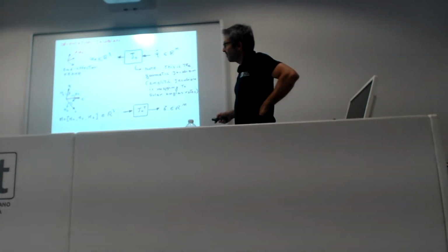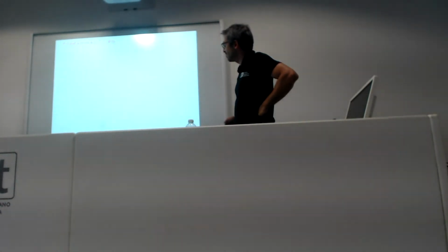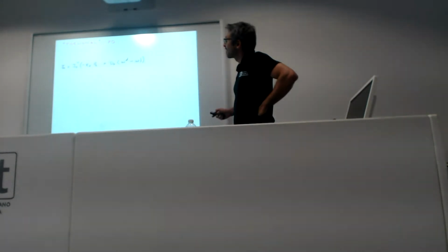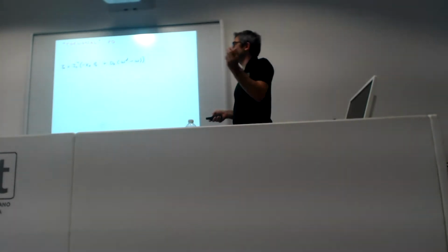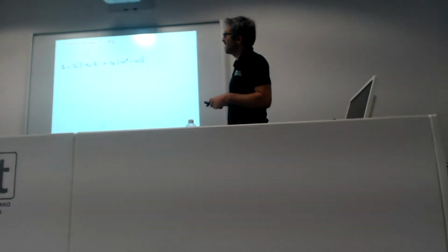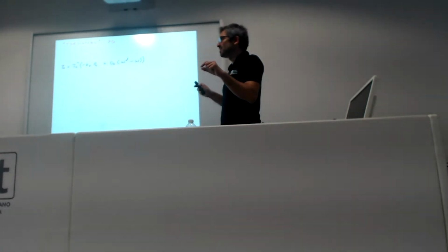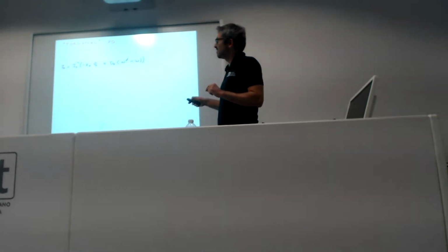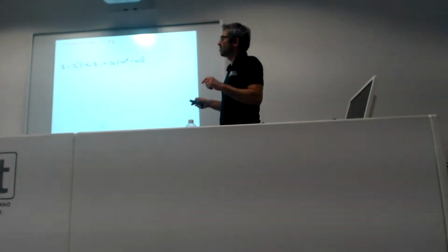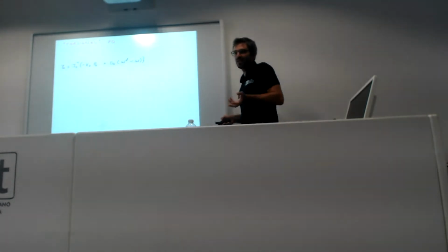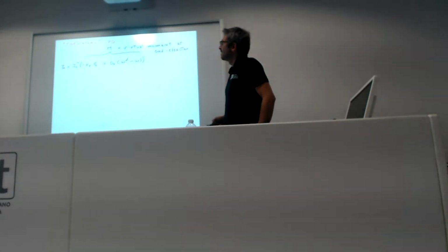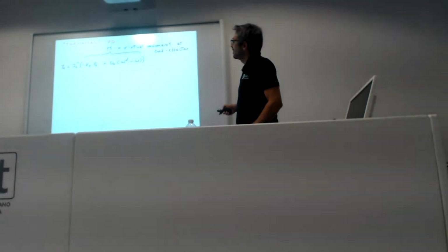So once we have the moment, we can get the tau. In general what we do, we have a PD, and the orientation error, we put a negative sign because we want to drive the orientation error to 0. So it's like saying k theta times 0 minus E orientation. So it means that the reference value for the orientation is, of course, 0. This is the virtual moment at the end effector.